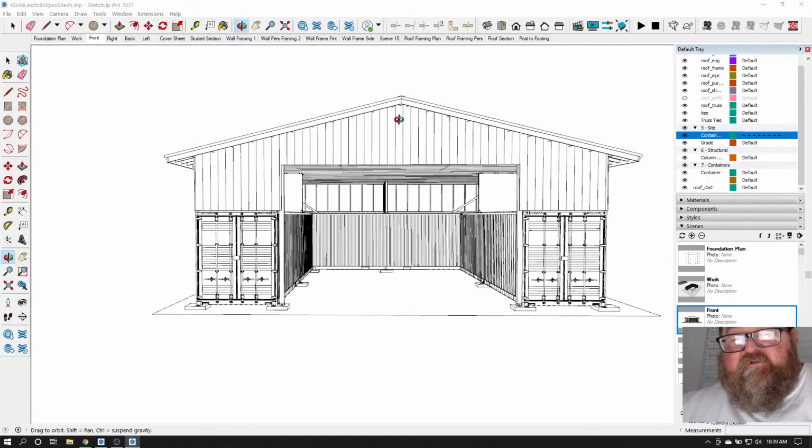She would want, like on this elevation, all the edges at like 0.5, and then all these lines at like 0.25, and she would go through the drawing. If the drawing was contextually perfect, she would go around with her marker and make changes to the line weights.